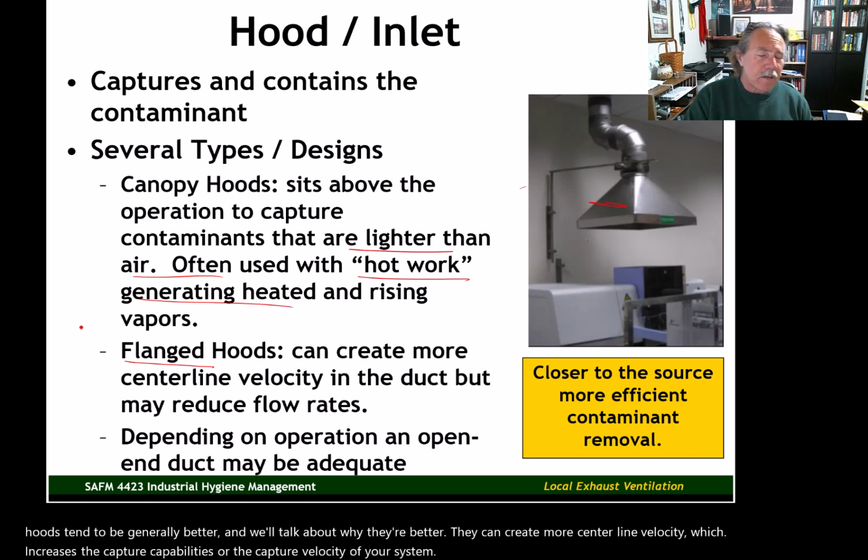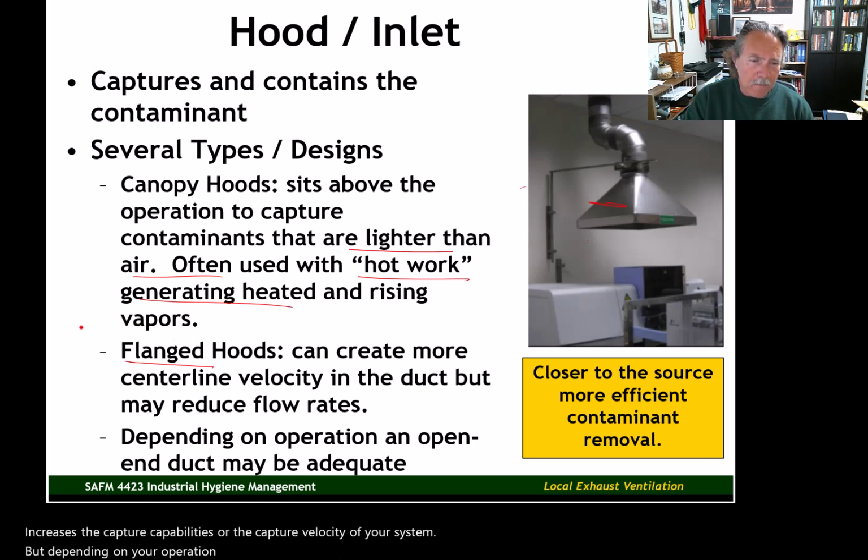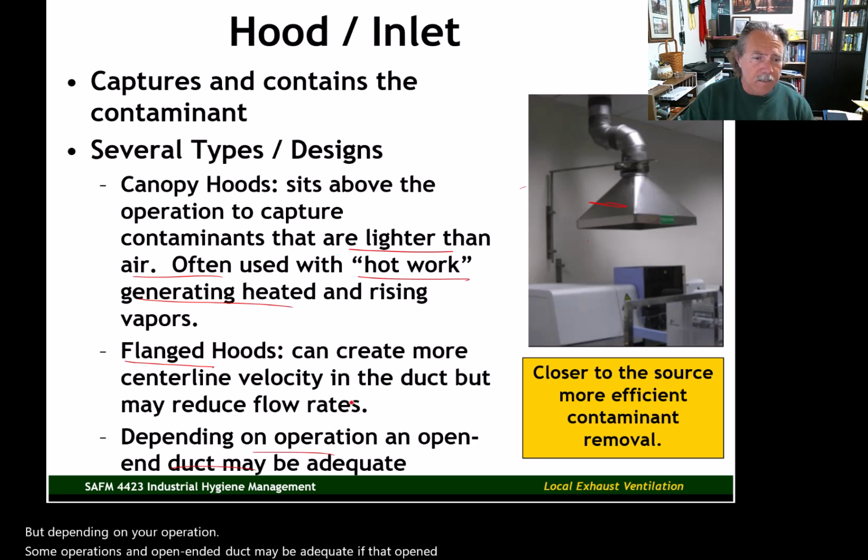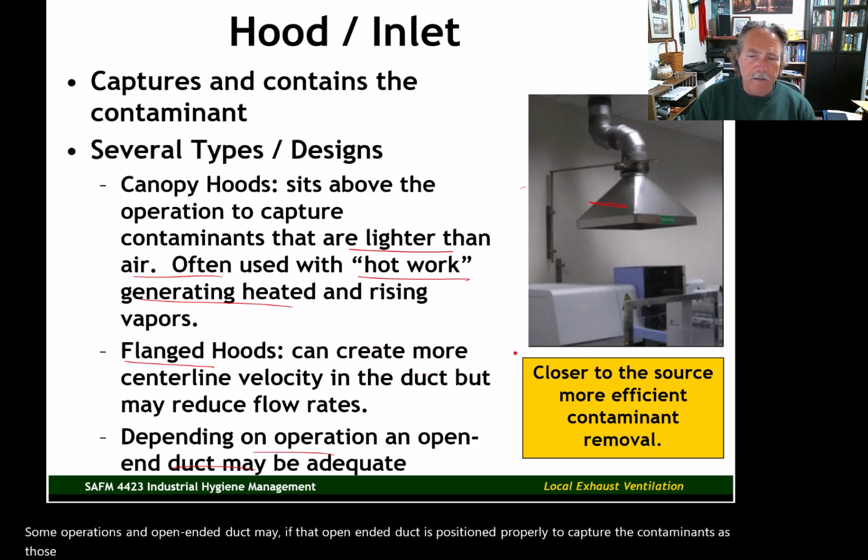But depending on your operation, an open-ended duct may be adequate if that open-ended duct is positioned properly to capture the contaminants as they are being generated.